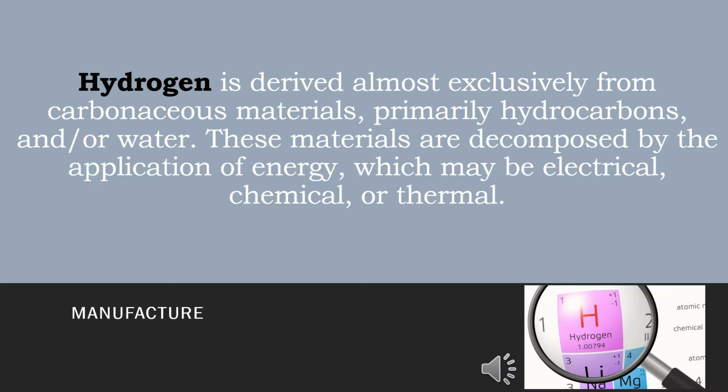Hydrogen is also produced by partial oxidation of hydrocarbons and by such less important methods as the steam iron process, water gas and producer gas processes, and separation from coke oven gas and refinery gas streams. Diffusion through a palladium-silver alloy furnishes very high purity hydrogen.